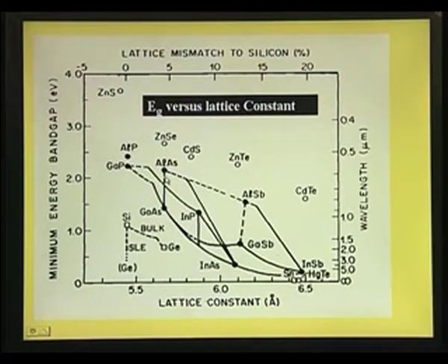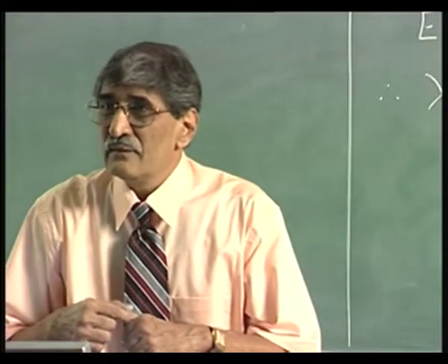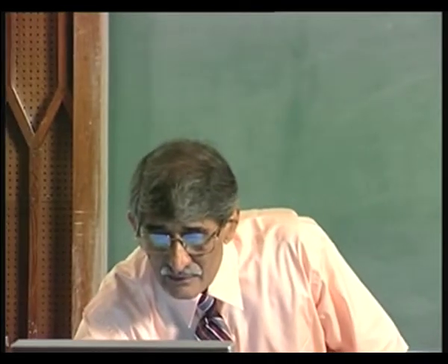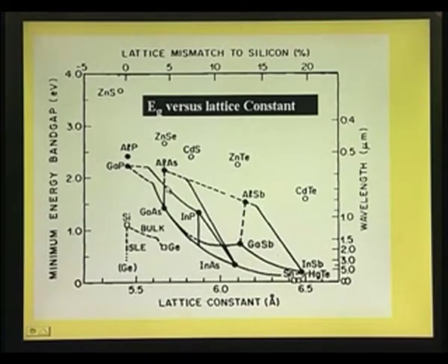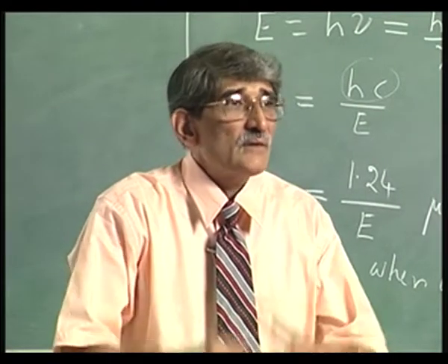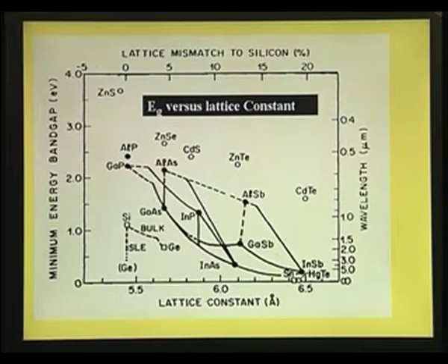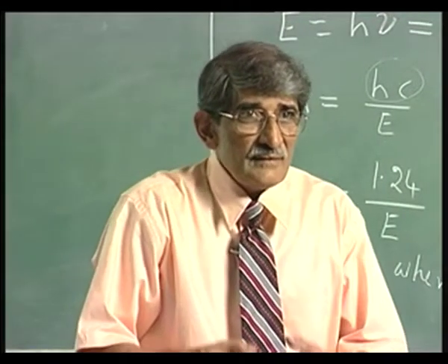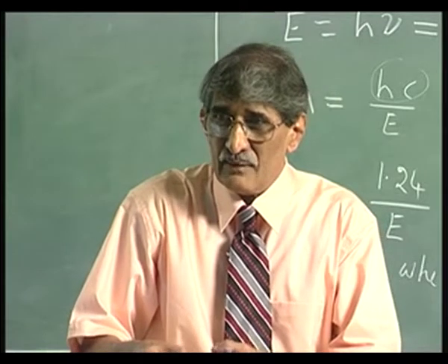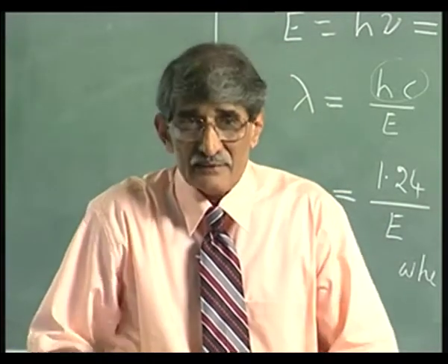You can mix gallium arsenide with aluminum arsenide, but aluminum arsenide is indirect band gap. So, if I mix that, as you go up increasing aluminum content, it becomes from direct to indirect. But again what you are saying is, you can have gallium arsenide, and on top of that you can have a compound made up of any composition from here to here. On the gallium arsenide, I can have aluminum gallium arsenide, that is, keep on adding aluminum to gallium arsenide, and it becomes aluminum gallium arsenide. I can have that.